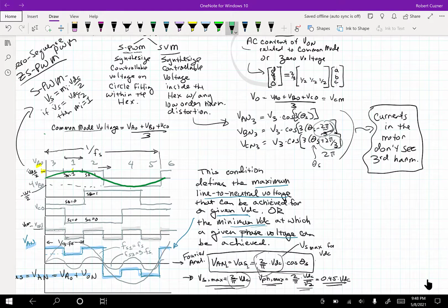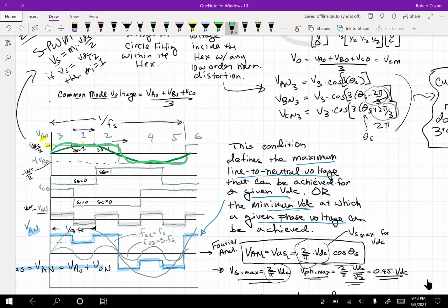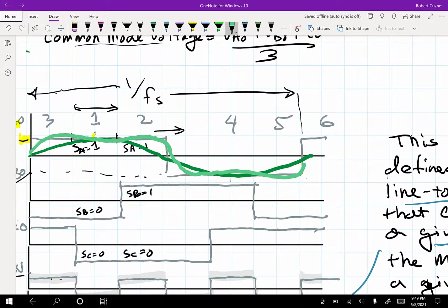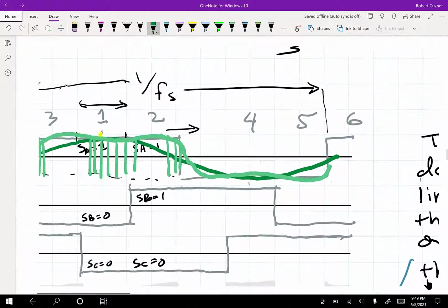And by what I've done there is I'm running right on this, and the results are that the synthesized voltages against the references, when I am running below, I'm actually going to get switching between every part of the waveform that is inside of that VDC over 2 envelope. So for the green one, obviously it would be pulse width modulated all of the way. And the same thing with the other 3 voltages.